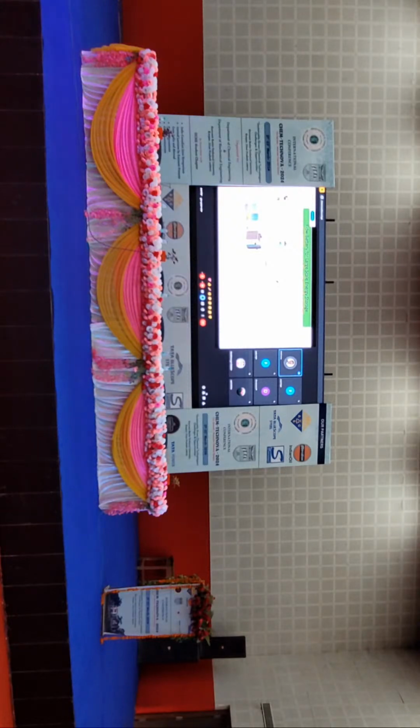Energy is stored in this flow battery, with power and energy decoupled. Decoupled power and energy means this particular section, this reactor, is responsible for the power. You see here, schematically it is shown over here. In the VRFB stack, a lot of cells are there in series. Once it is running, this stack will provide the power, whereas the amount of liquid in these two tanks will tell me how much the energy is.